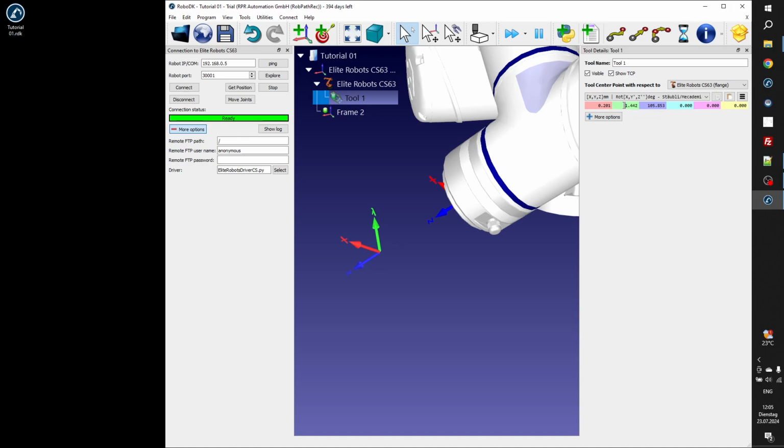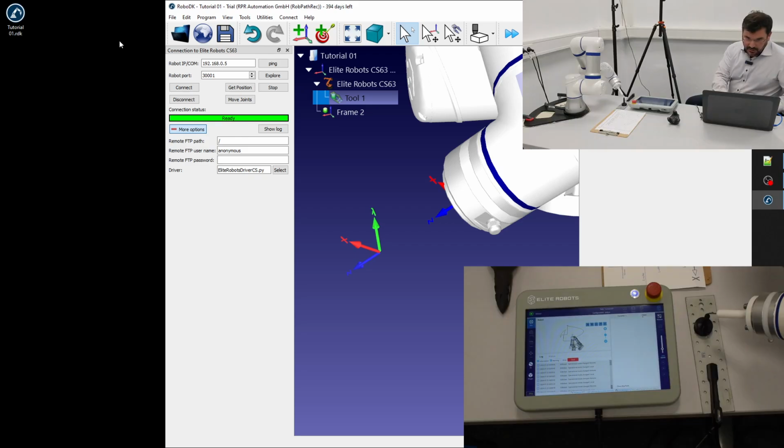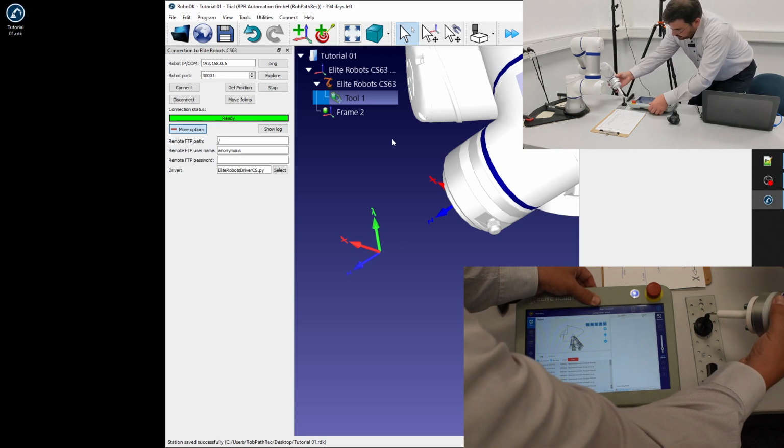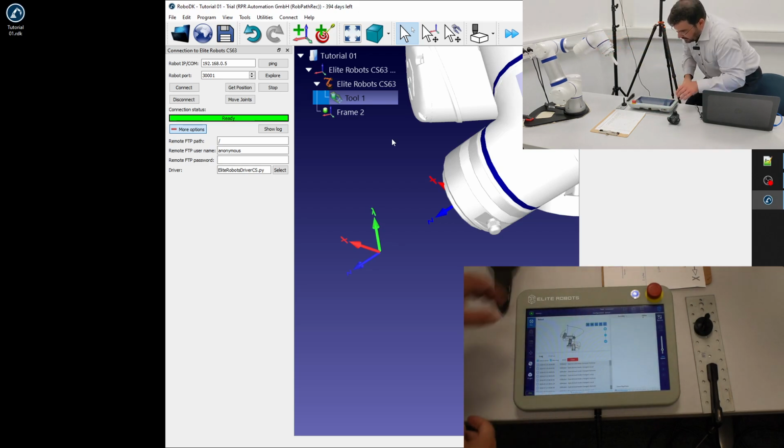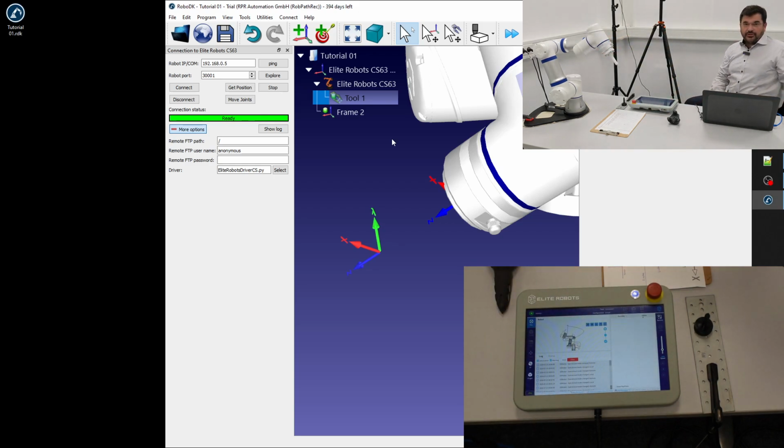If you can really follow where the point of the tool should be, then this is easygoing, and you can even define it manually. The value of 105.8 seems to be quite valid. The 0.2 is excellent. So overall, I think this tool calibration was a good one. I just hit record, hit the save button again, and come back to a normal neutral position with the robot. Okay, and we will move to the next step.